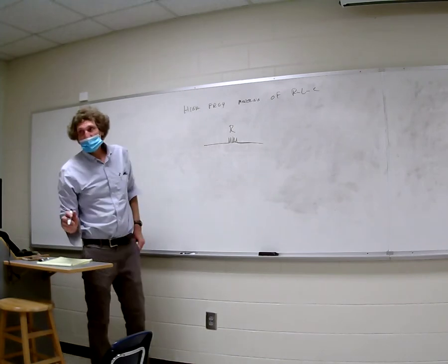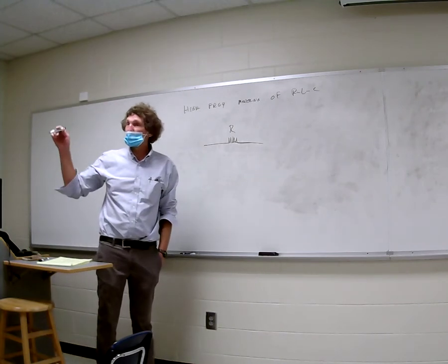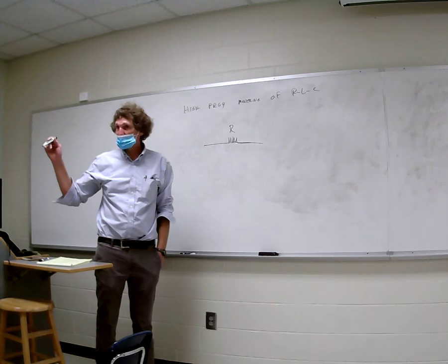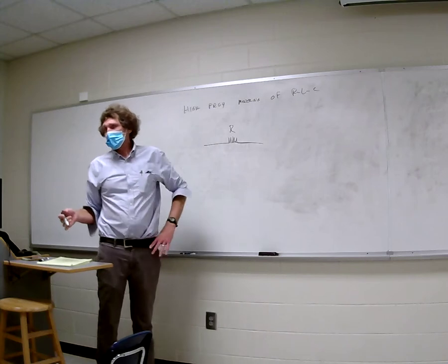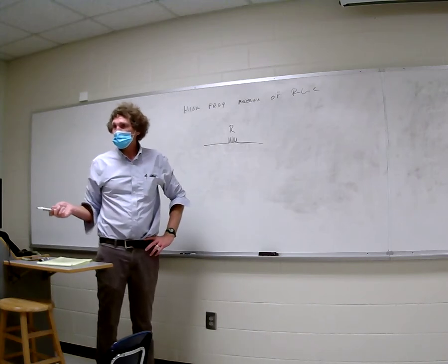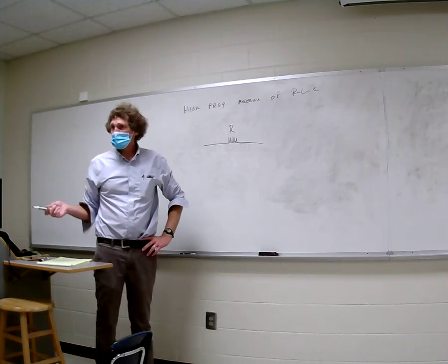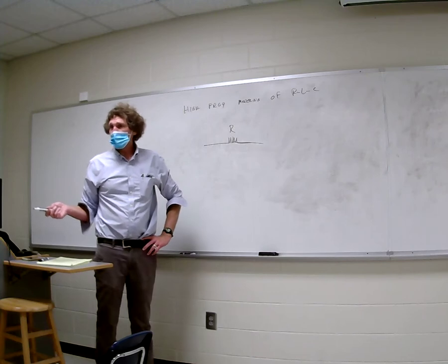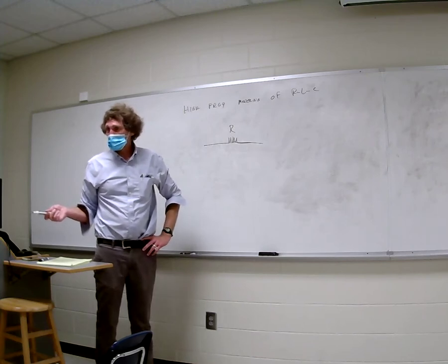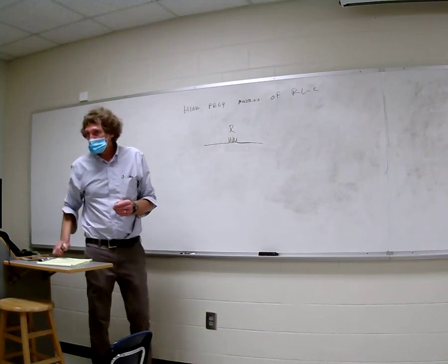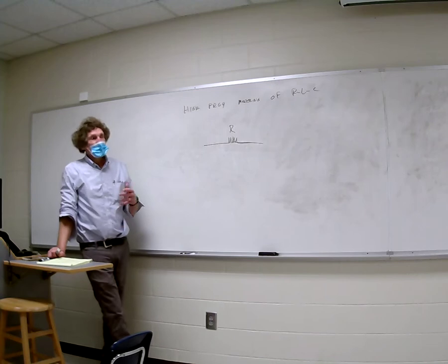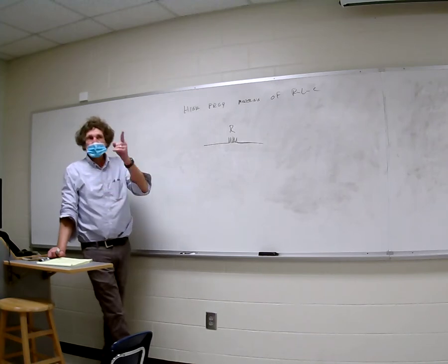The real thing you have to worry about is there's a silver or gold line at the end. Do you remember what those are? Tolerance. Gold is the good one. Just remember that, G for good. That's less than 5%, and silver's 10%, I think, unless they've changed that. And if you want 1%, I'm not even sure how to get that anymore. That's a certain spec. Anyway, that's a resistor. Could be a carbon resistor, but resistors can be anything. You can have resistors that are serpentine lines.